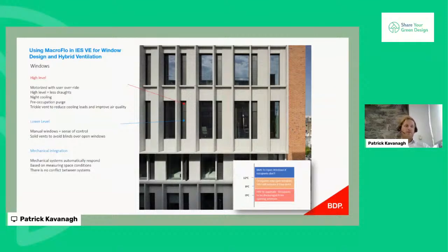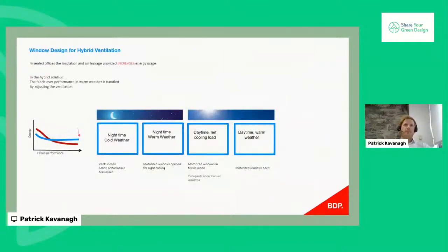If it's between kind of 6 to 12 degrees, the occupants can open the windows. And if they don't, and the CO2 levels start going up, the heat recovery ventilation will kick in. And then below kind of 6 degrees, the heat recovery will operate and the occupants will be discouraged from opening windows. So there's a little delay on it. And basically it just means that it maintains the fabric resilience and the design that we went to good lengths to try and achieve during colder weather.